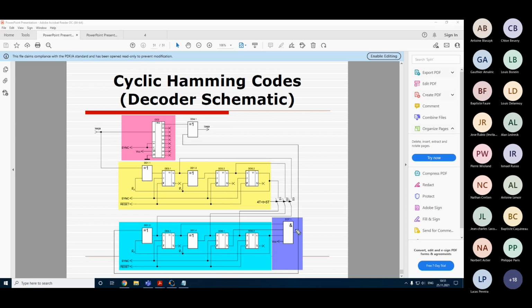Yes, so basically the error detector is an AND function, which is connected so that we read from these flip-flops our dedicated syndrome. So basically here we take the direct output because we should consider 1. Here we take the inverse output, so that this 0 is converted into 1, and here we take the direct output, so it's also 1.